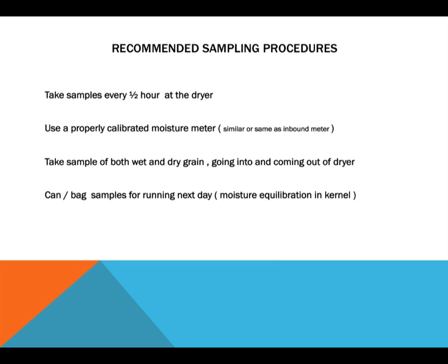Sampling. Now this holds true. You don't have to do this during your test. Okay, you can if you want. It's not really important. This is really a sampling procedure when your dryer is operating. I would recommend that you take samples every half an hour at the dryer.